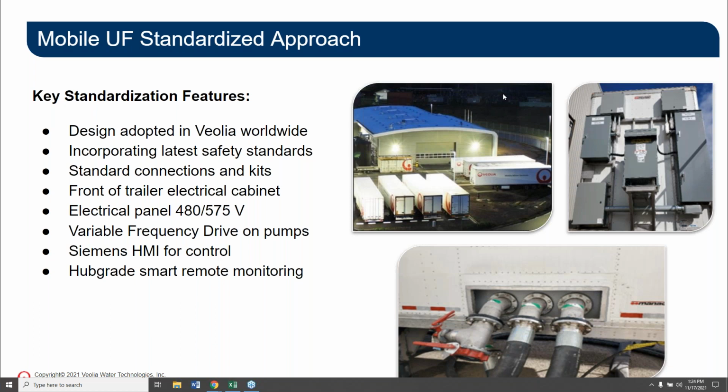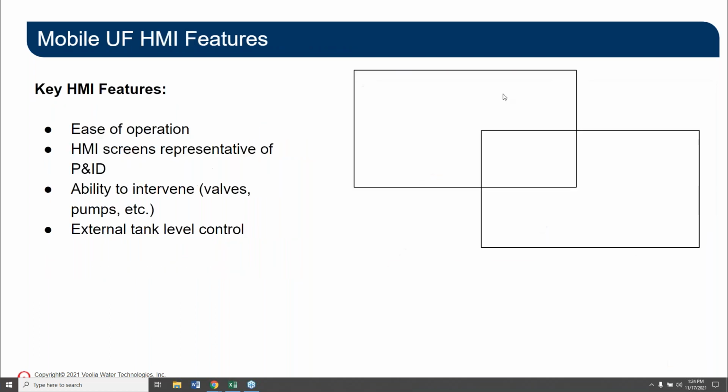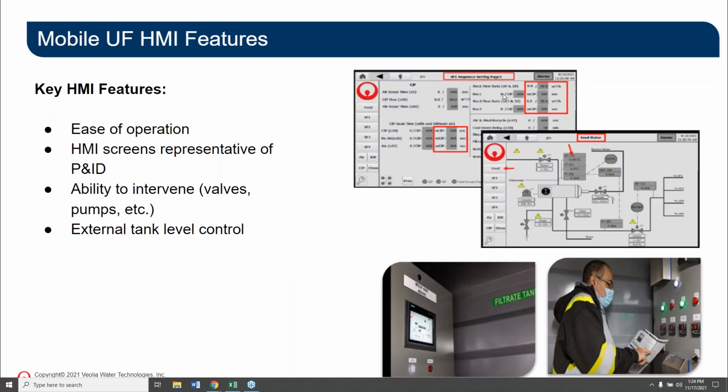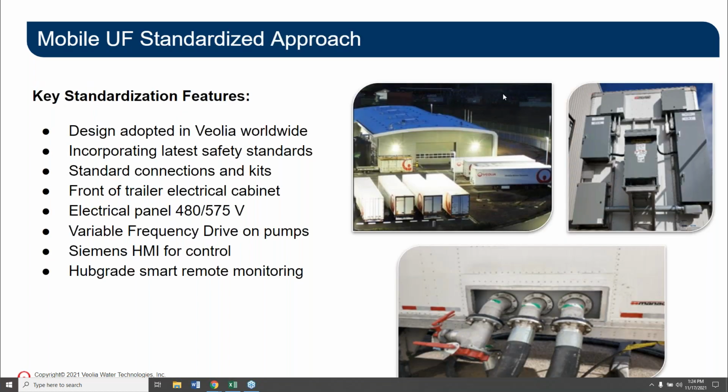water. We also believe that it has a reduced OPEX compared to other solutions, thanks to the fact that pre-coagulation is not required. And as you know, the coagulant is probably the single major OPEX component in a UF system, so that is out of your way. Next slide.